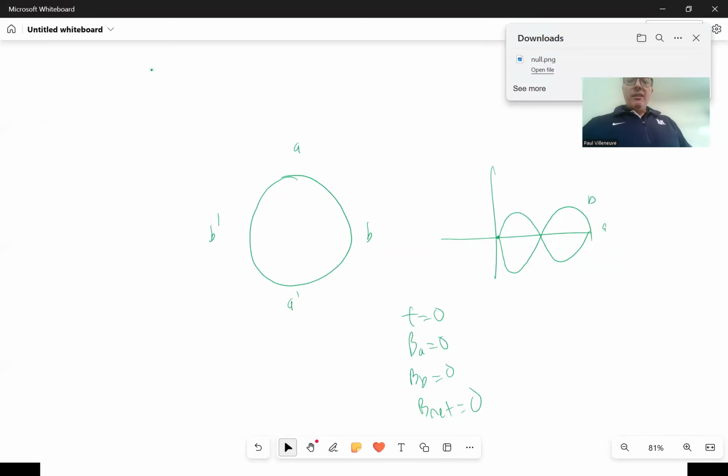So let's go to 90 degrees, okay? We see that BA is positive, so we've got maximum current going into A. We'll show that as an X here and a point here. My magnetic field, this is BA when we're at 90 degrees. Now I'm trying to calculate my B sub B, which tells me I have negative maximum current. So here's my X and here's my O. When I do my fingers, I get a B sub B here.